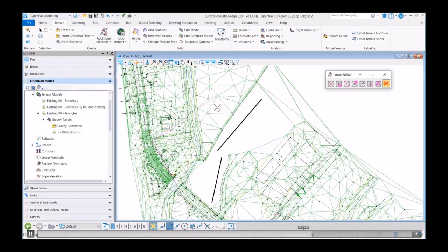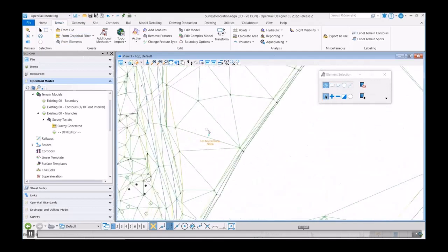It remembers the edits now through these transient graphics. So if you want to delete those edits or remove them, just delete that transient graphic with that icon enabled, and those edits will be removed and the triangles will come back. So not only are we allowing you to edit a live terrain, we're actually remembering the edits.